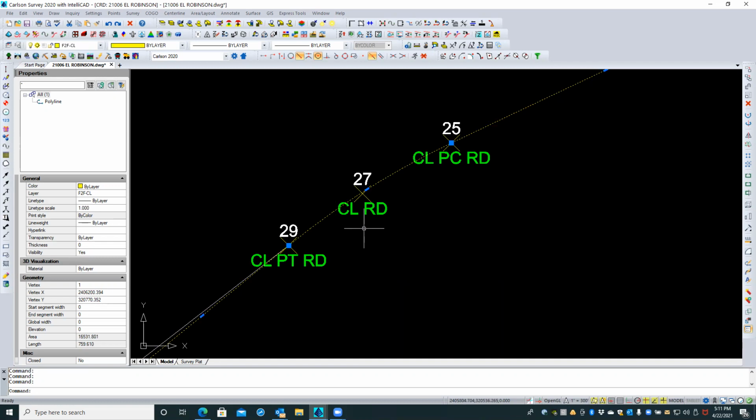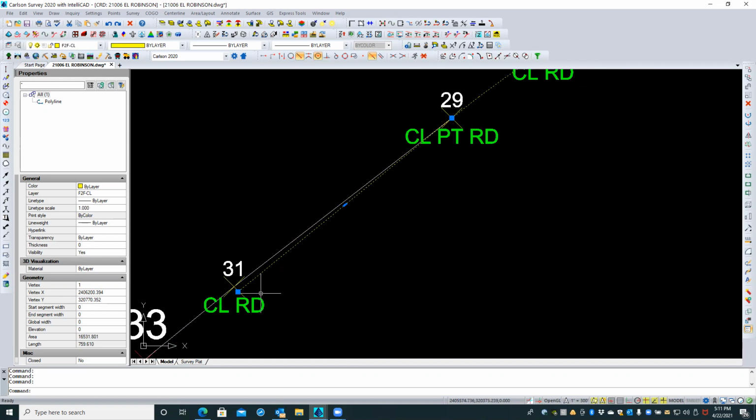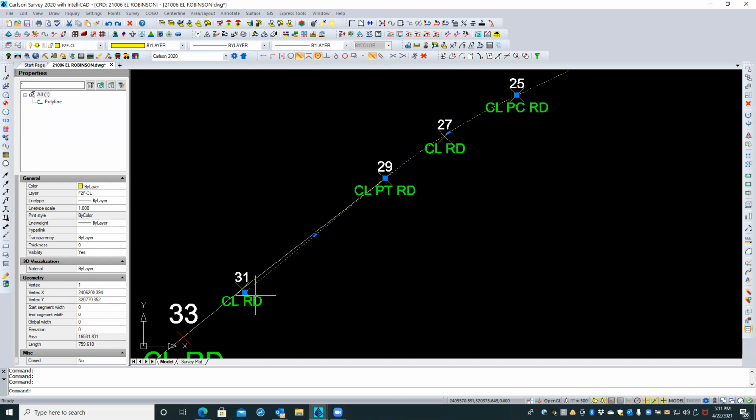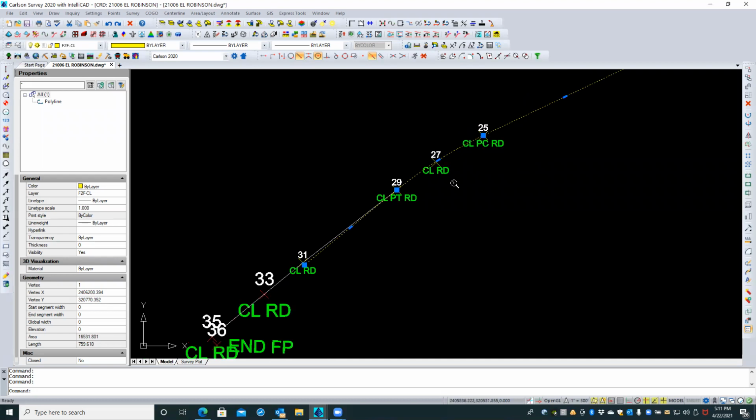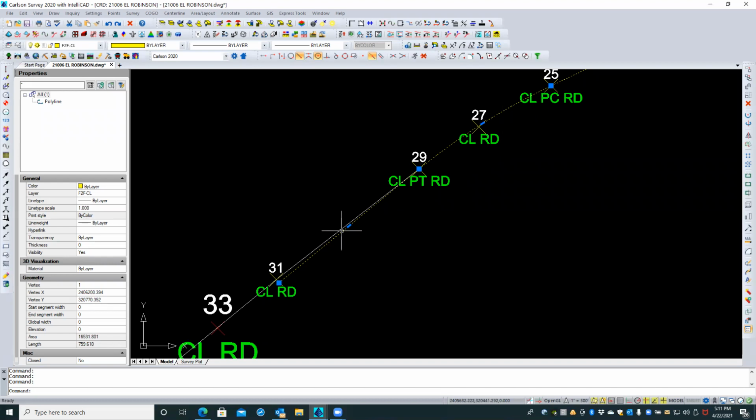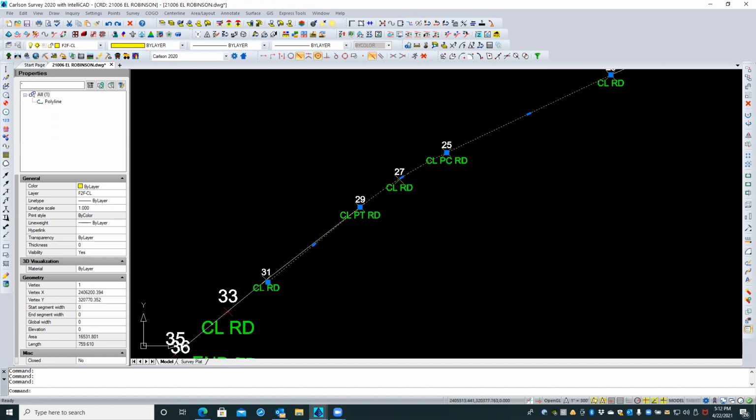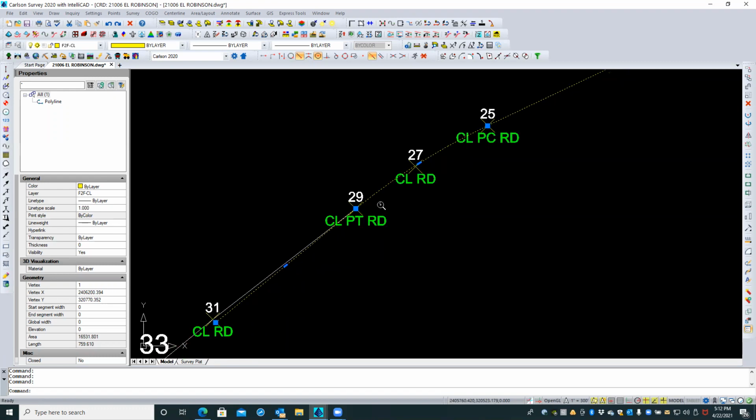Well, I didn't like any one of them. Okay, so that didn't work the way it's supposed to work, because what should have happened there is, when field to finish puts this in tangentially from this back section and we allow it to adjust, then going into the alignment, making it tangential and making the outcoming segment tangential should keep this back here up on that line somewhere, not necessarily exactly on that point, but at least on that line. And that did not happen.